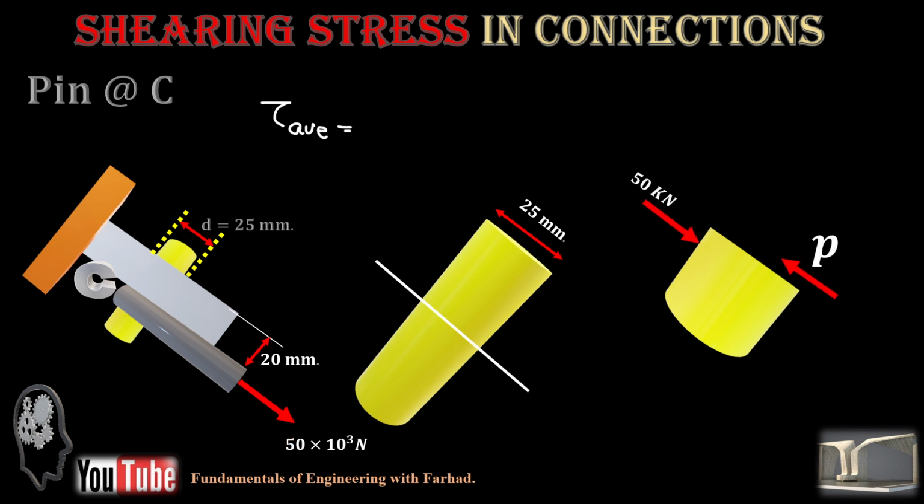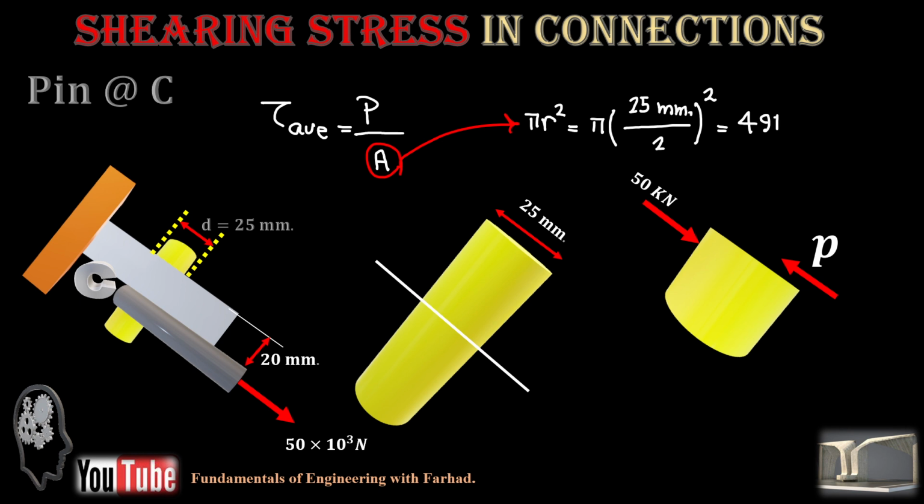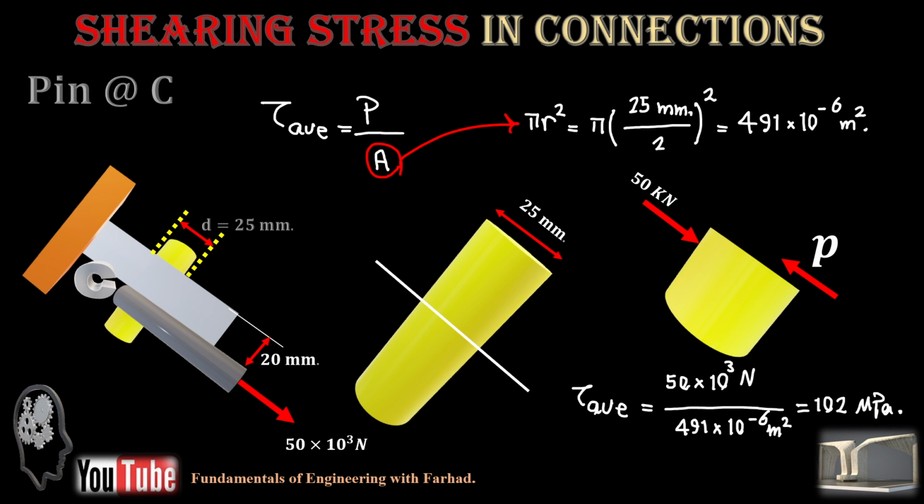It's simple: at single shear, we divide the force by the area of the pin, which is pi times 25 over 2, the radius, squared. Tau average is force over area, and because it's single shear, you simply use the area in the formula. It gives you 102 megapascal for the pin at C, which is in single shear.